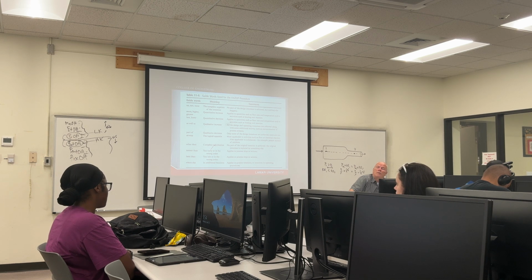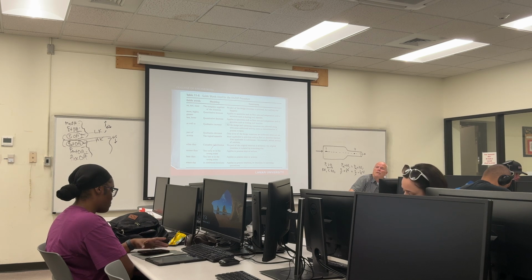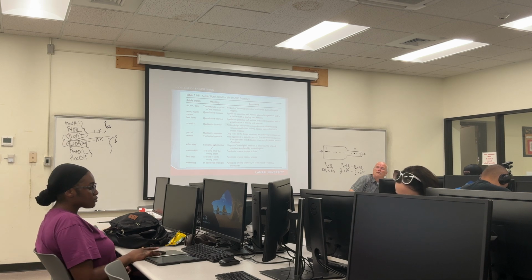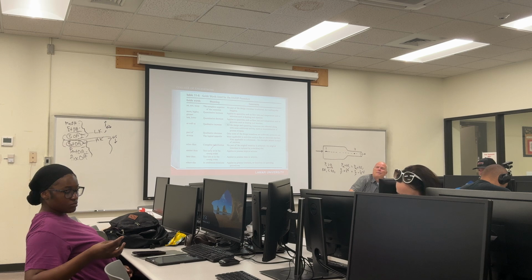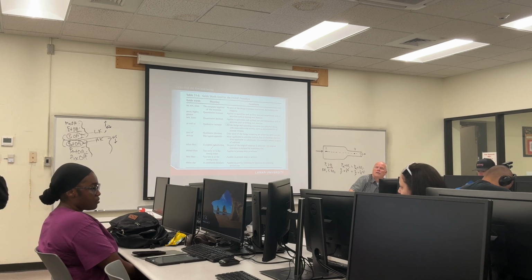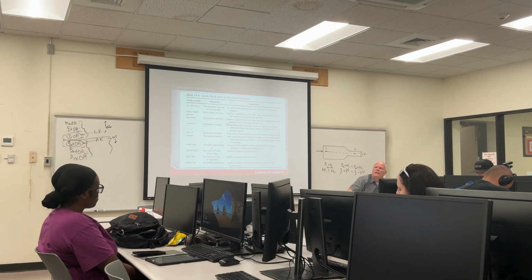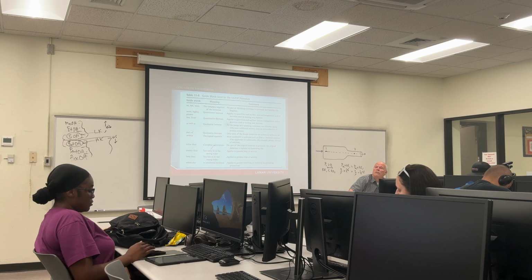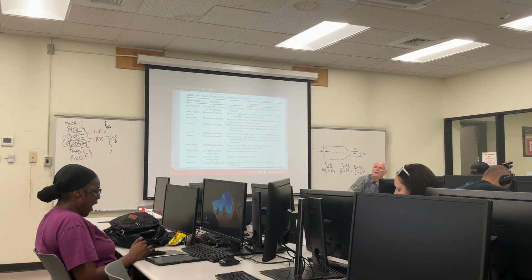Yeah, well, I mean, you could come up with, say, okay, my reboiler fills up and overflows. So you keep having feed coming in, the reboiler stops working, and I can't get out the bottom because it's too much, and the reboiler overflows. You could think out a scenario like that. That would be a reasonable thing to think about, I think. But on the whole, you would probably struggle to come up with anything that would cause a big risk, a big event, for a reboiler stopping working.